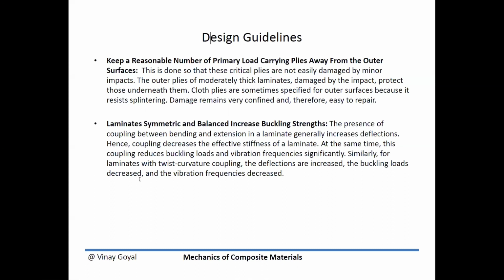However, it's possible you're going to have subsurface damage. And so when you encounter that, it's important to perform some amount of non-destructive evaluation to find these potential damages that are hidden from the impact events. The inner plies are carrying most of the load within the composite, and then the outer plies are more there to protect you.